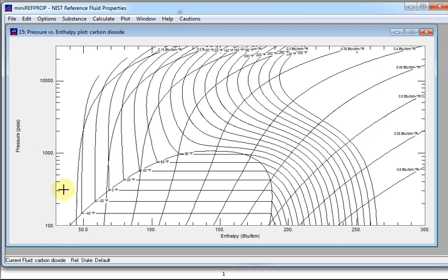So what we can do here is we plotted these lines of constant S. Why did we plot lines of constant S? Because in our traditional vapor compression refrigeration, what comes out of the evaporator is saturated vapor, somewhere along here, saturated vapor, right? And if you had a great compressor, it would be isentropic. It would follow a line of constant S going up. That's why we put a nice line of constant entropy on this pH diagram.